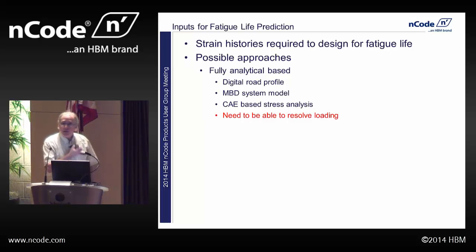And one is fully analytical, and you'll see some of this today looking at the auto companies where they can literally have a digitized proving ground, run multi-body dynamics codes around a car around the track with specific tire models, recover all the loads in the structure, and use that downstream in fatigue analysis. And the key here is you need to be able to quantify that interaction for the loads. And so, you know, today we can look at a tire model on a paved road, but it may not be appropriate for construction equipment digging into the ground or things where we can't really quantify the load interaction. But if we can, this is one approach for doing that.